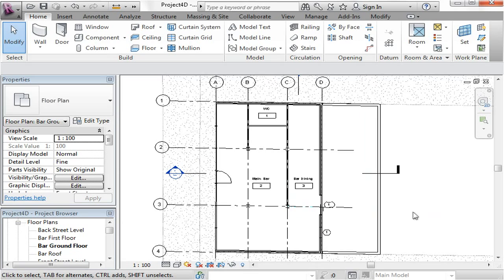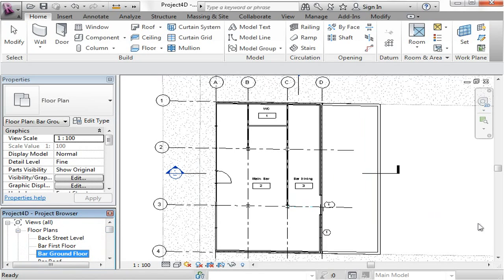Now, the process of extracting 2D drawings is very much minimal. They've already been provided in all the floor plans, elevations and section views that you've been working with to date. So the views are there and they are also your 2D drawing. So what you will be doing is just bringing in those views onto a sheet. So that's as far as extracting 2D drawing goes.